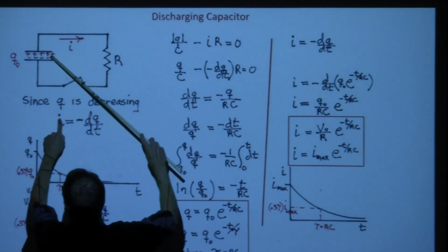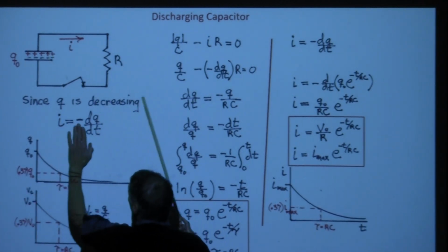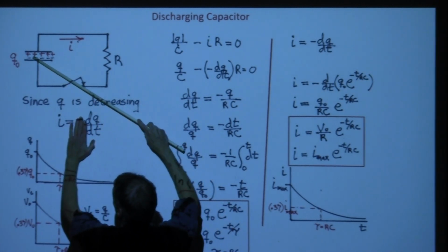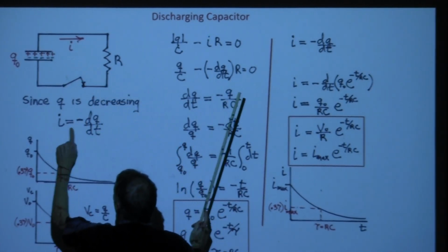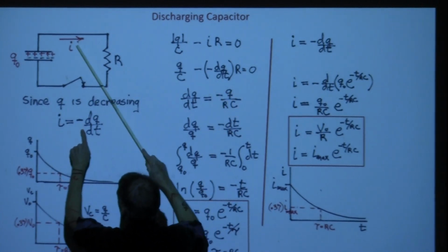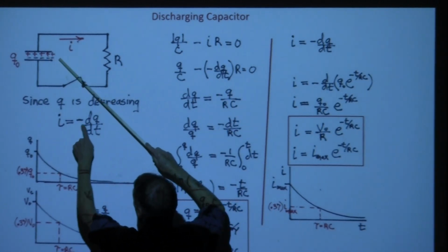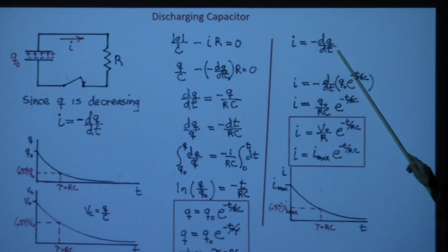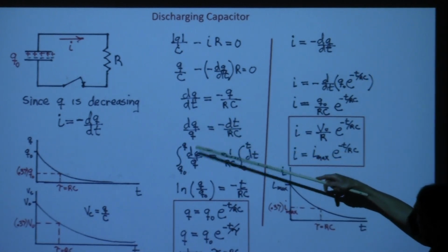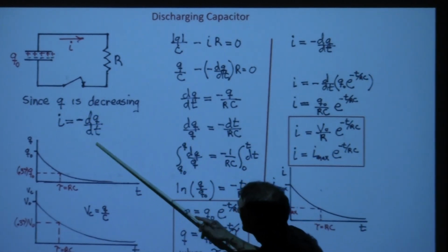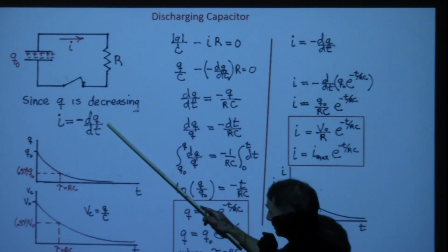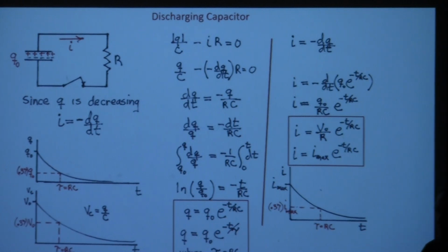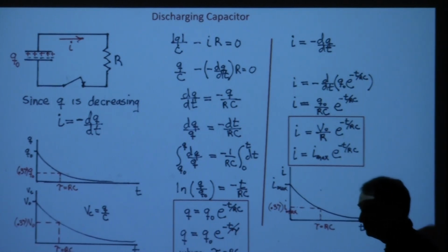And also the Q on this, I don't want to say it's dQ/dt, because that represents the charge on the capacitor. So as this drops, the current would be the opposite sign. So this is plus, that is plus, but this will be minus. And so I picked that up here with that same sign convention. This is probably the trickiest part of discharging the capacitor, seeing this relationship or missing it, and then you mess up your math. But that's just showing that the direction of current changes.